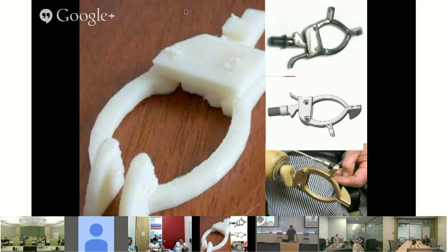So what we discovered is that the one in the lower right was printed using a selective laser sintering rapid prototyping process, and we had some tolerance problems with that one until the Service Bureau actually printed the thing out on a plate and then machined off the plate. The two jaws of the hook did not fit together, so we had something like more than 50 thousandths off on that thing. I bring this up just to point out the limitations of some of these things.